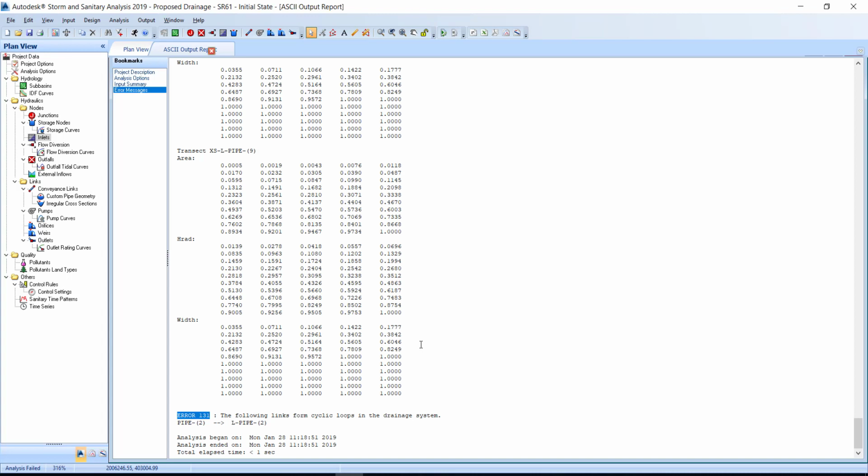So in this case, the pavement gutter is bypassing S3 and flowing toward S2, which is a sag inlet, but the pipe connected to S2 flows to S3. The design is correct, but the internal logic in SSA views the bypass link to be pointing to an upstream node, which it deems invalid. Ultimately, the bypass flow from S3 will go downstream to S13, and we must configure the bypass link for S3 to agree with this logic.